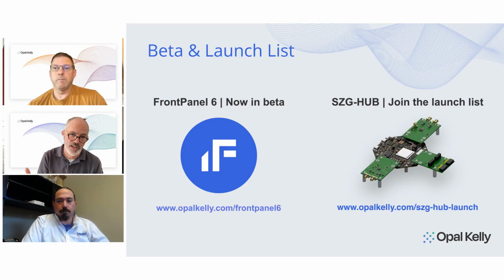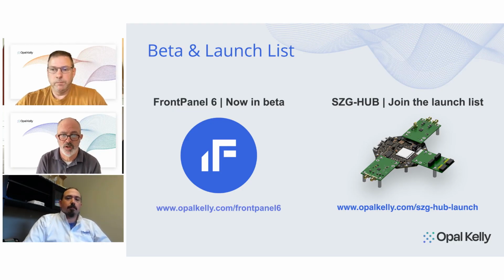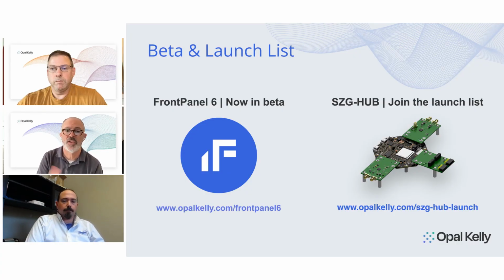On the FPGA, you have an inherently low jitter, high bandwidth control environment, where you can run your PID or other control schemes in hardware, isolated from all the uncertainties of the PC environment, the determinism and problems that you would have on the PC side. So that's another very common application of using an FPGA out at the end of a USB cable. And then the USB cable is providing command and control to that control system at the end of the cable. So those are a couple examples of typical applications.